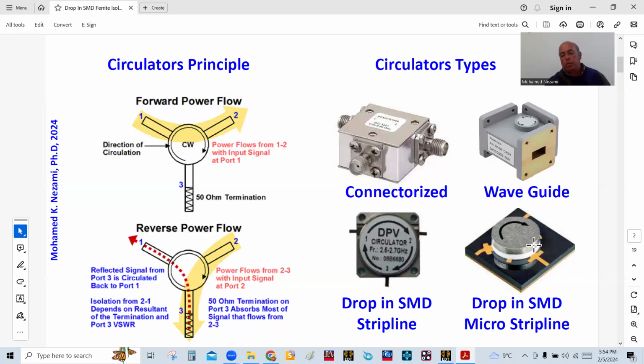Or a microstrip, and a microstrip you can see here. So you've got a ground plane, you've got a substrate, in this case this black piece here, and then you've got a stack of 3 things. You've got the ferrite material, which is here, and a spacer, which is basically just a piece of foam, mechanically isolating and just placing the magnet. This is the permanent magnet, with the ferrite on top of it. You don't have to make a cutout on the board for it like you would for a stripline.